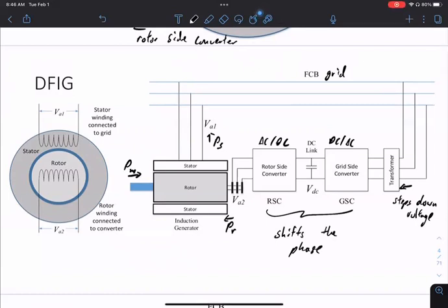The voltage source now developed in this rotor can have a different phase in the current coming out. And you have this V times I, with the angle between them, and based on this angle you can generate reactive power. So that's the main conceptual setup of a DFIG. The double feed comes in here: you have two paths of power flow. So this is your doubly fed induction generator.